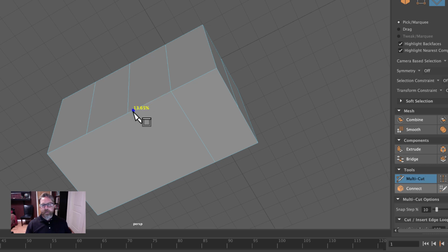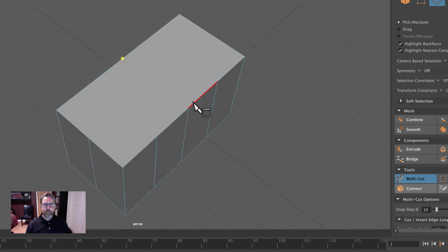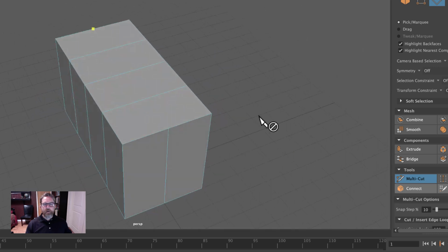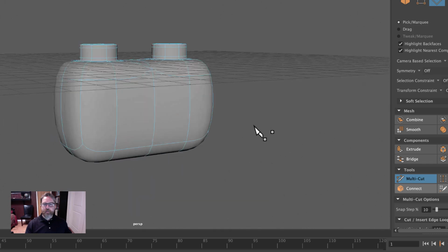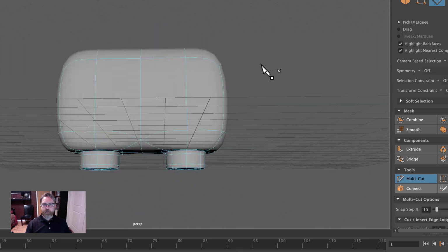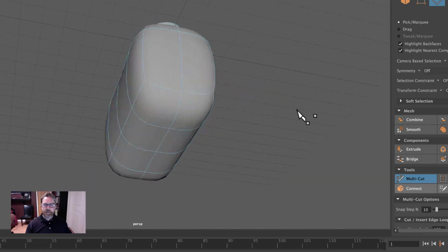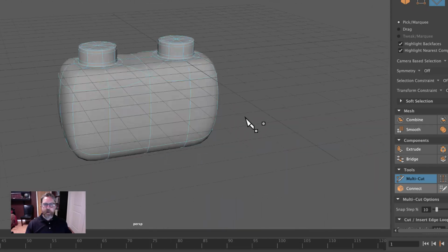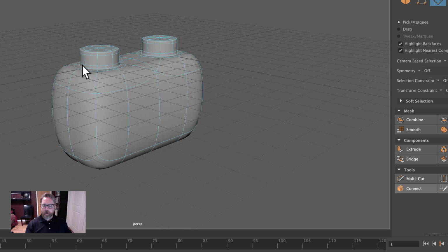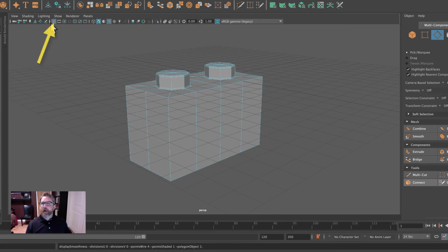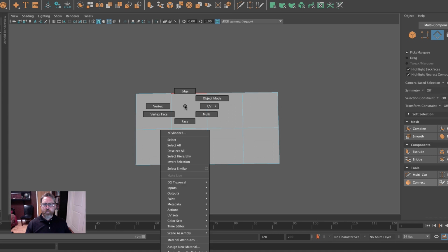And we'll just repeat that process. Click drag till it stops, come to the other side, click drag, and then return or enter on the keyboard. Click drag and click drag, return, and then we've got one across. Click drag and we'll dolly around, click drag, and we'll hit return. And if we hit the 3 key, we can see that the mesh is indeed 4-sided, but it's soft. We'll eventually bevel those edges to keep them hard. Come back to the 1 mode, and I'm going to hide my grid, and we'll extrude.